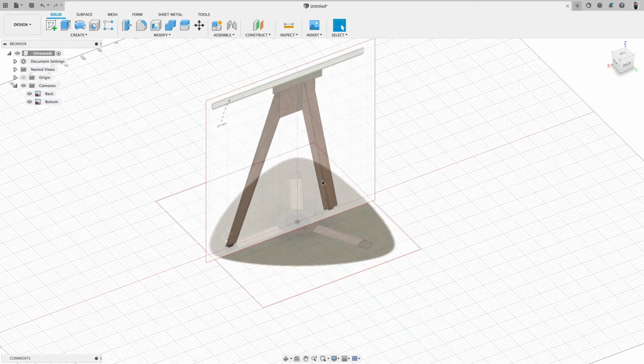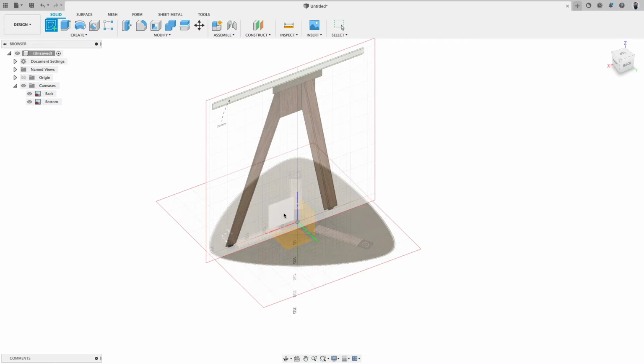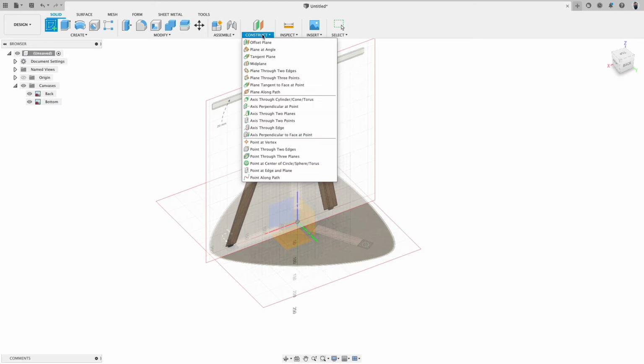Okay, very good. So we would like to create the tabletop. I need to sketch actually at this height. Okay, if I go create sketch, I only have these three planes to put a sketch onto. And when I create a sketch, I can't just move it. So what we have to do first is create, right along this height, a construction plane.